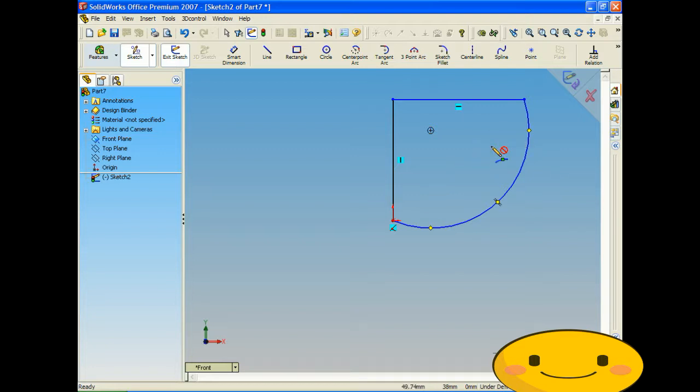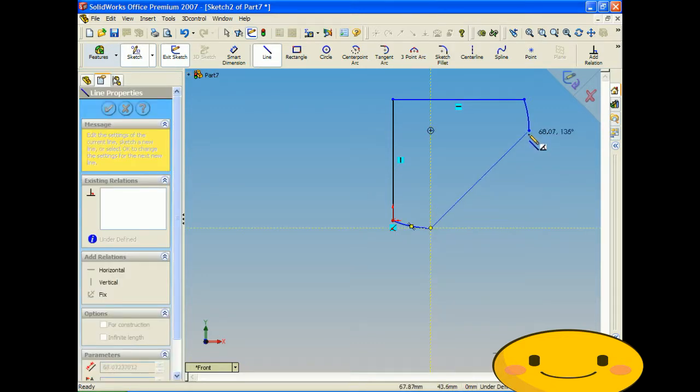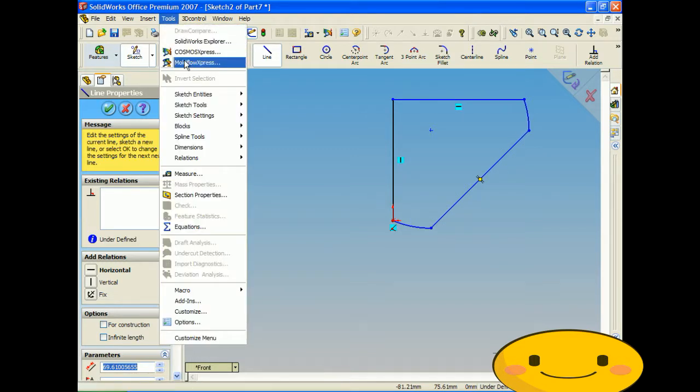So let's say that we want the whole sketch minus from this point to this point. So what we want to do is click this point here and this point here, then click the select button and select that section in the middle, click delete, and we've gotten rid of it. And let's just close it up, say we want a straight line there, and now we have the straight line there. So with this, the split entities, what it allows you to do is just keep sectioning off one specific line or sketch, whatever it may look like.